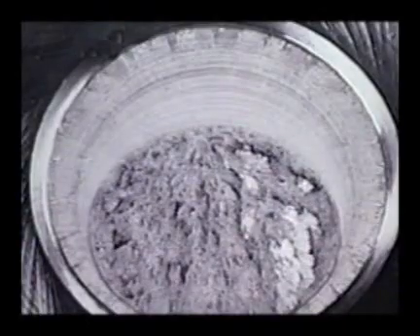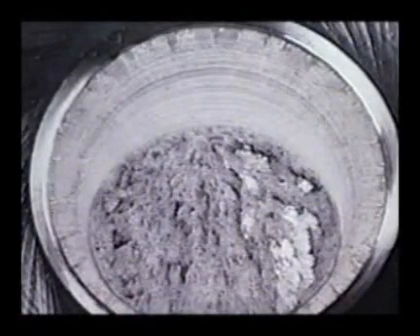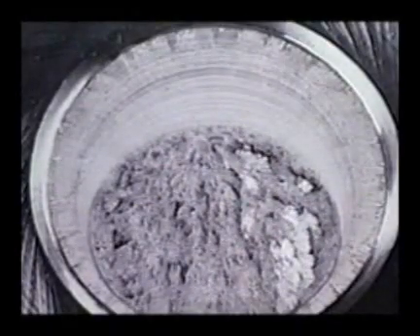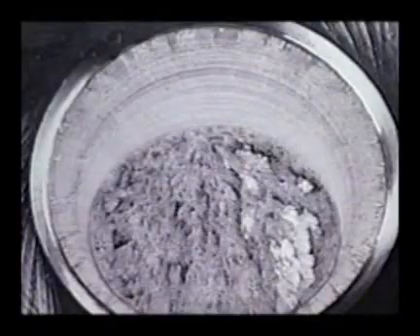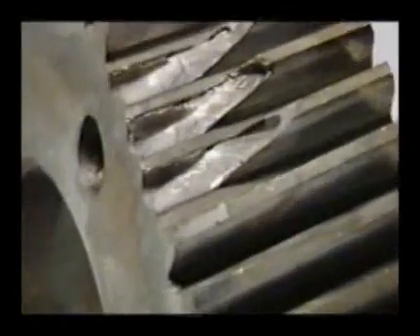Fatigue crack surface features depend on load type. Tensile fatigue produces beach marks that are circular and concentric to the circumference. These fractures may initiate on the outside with final fracture beneath the surface, or they may start beneath the surface and grow outward. Bending fatigue produces beach marks that start at one location and spread outward towards the other side of the part, like ripples on water.